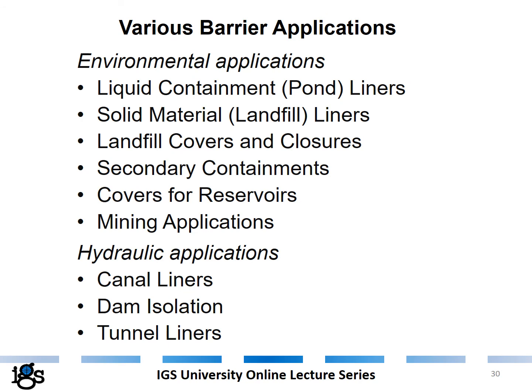There are various barrier applications. I have listed them under two main headings. One is the environmental applications, and the other is the hydraulic applications. Among environmental applications, we can count liquid containment or pond liners, solid material liners, or as we more often call them, landfills, landfill covers and closures, secondary containments, covers for reservoirs, and mining applications.